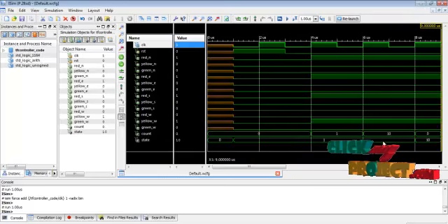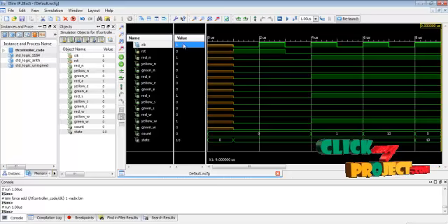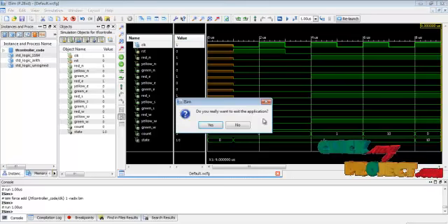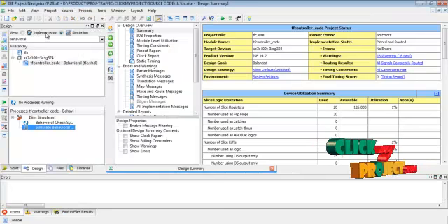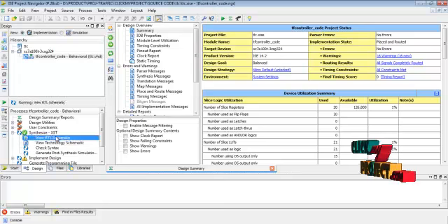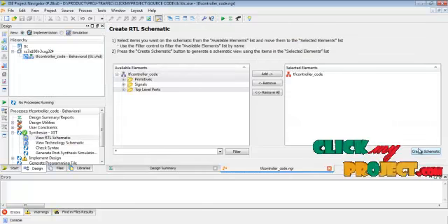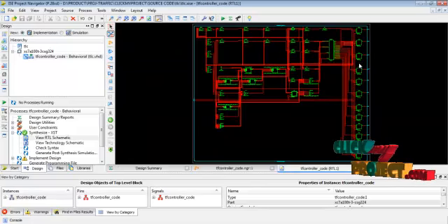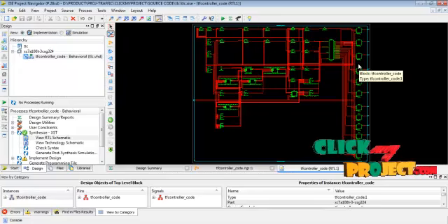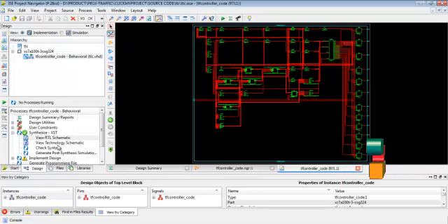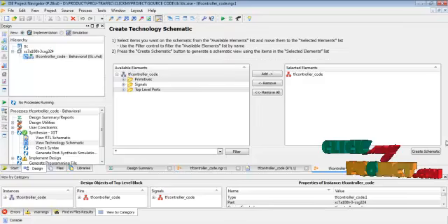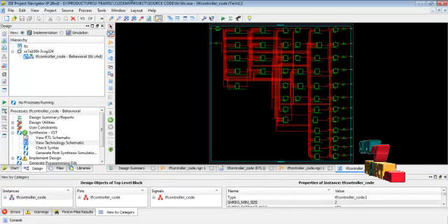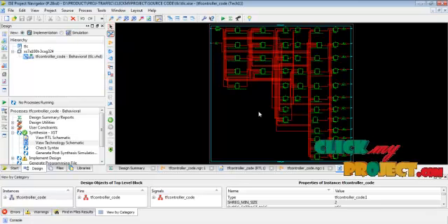These results change the overall architecture results based on our LED functions using the traffic light controller architecture, and then we select the implementation process. Then we see the view RTL process. This RTL diagram is mainly used to show the logical blocks, a register transfer level diagrammatic representation. Then we go to the view technology diagram. This technology diagram is mainly used to show the lookup table functions and input output, then the buffer position in the overall IC function.